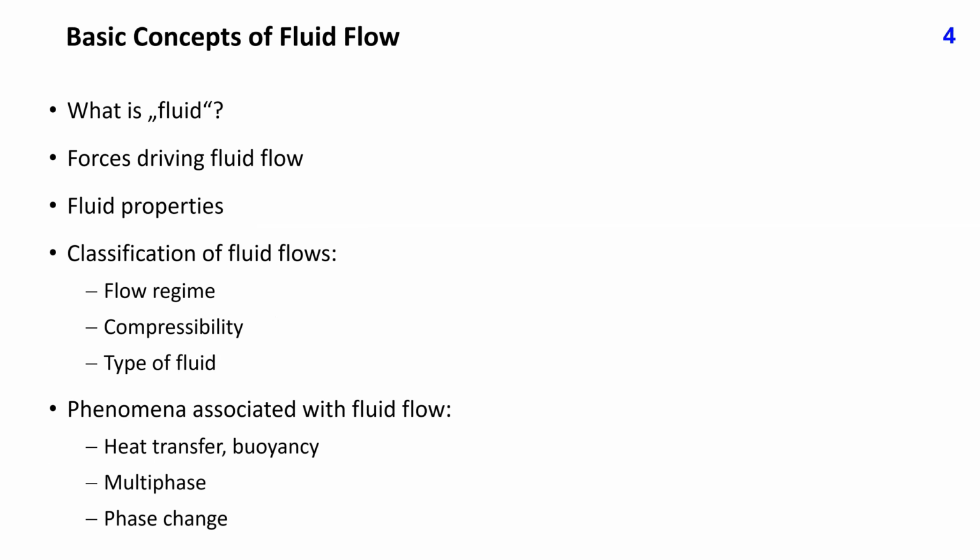We call fluid any substance which offers no resistance to external shear forces. Even the smallest shear force will cause the deformation of a fluid element. We distinguish between liquids and gases, but both kinds of fluid obey the same laws of motion, and in most practical cases of interest, we can consider them as a continuum. The forces which drive fluid flow can be classified as surface and body forces. Examples of surface forces are pressure, normal to surface, and shear, tangential to surface, while gravity and rotational forces are prominent examples of body forces.